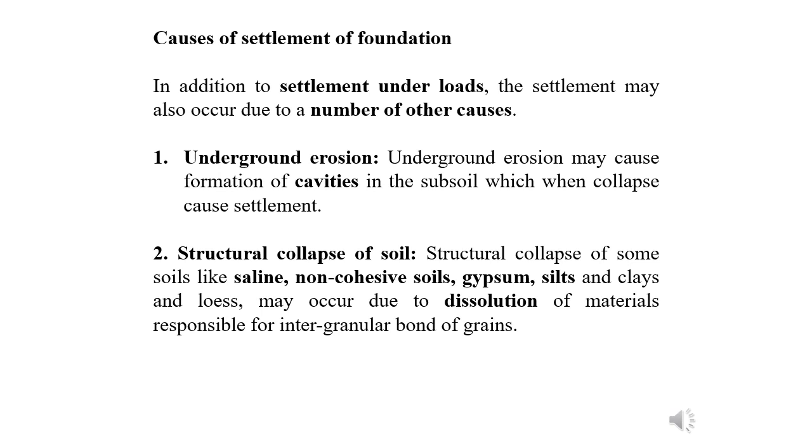Suppose the materials are available below the base of the footing: gypsum, silt, saline, right? These materials can be dissolved in the rainy seasons. So if these materials are going to dissolve, and they are available below the base of the footing, there is a chance of settlement.